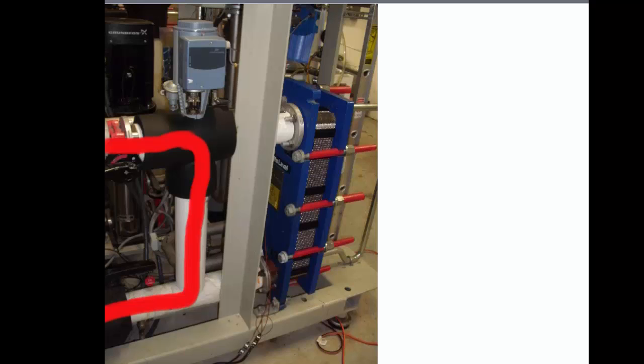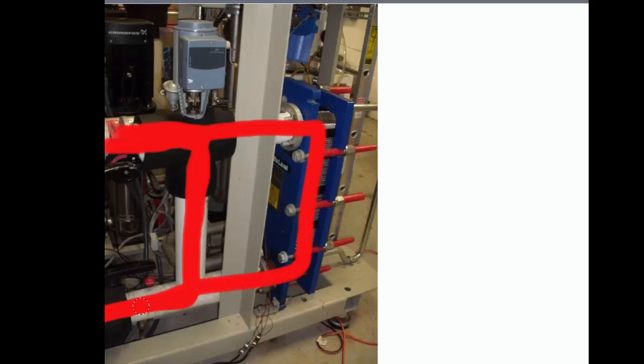If the valve closes a lot, it means we have a pretty high demand for chill water, in which case we may not have enough overhead for the P1. But if the valve opens, it means it's bypassing most of the chill water. And if it's bypassing most of the chill water, it means we have a significant overhead of chill water supply, in which case we can probably accommodate the P1. So usually it's halfway in between or somewhere in between, and we need to know where this lives on a regular basis.